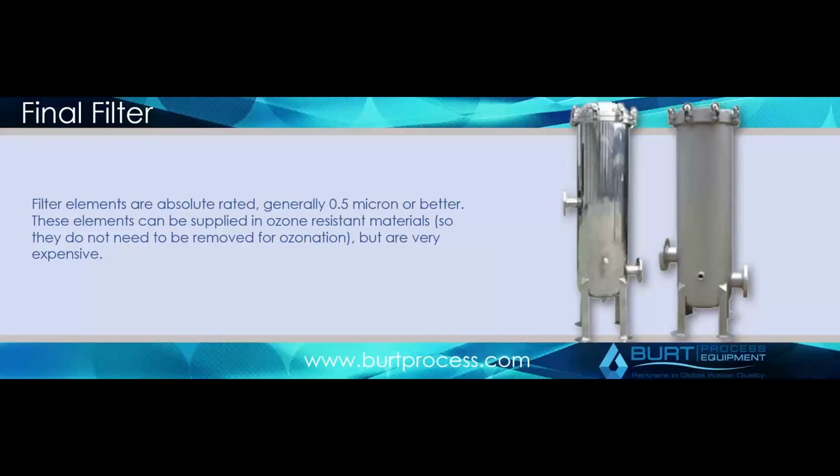And then lastly, one of the more common components in the system is the final filter, generally 0.2 to 0.5 micron or better. And they can go much lower than that, down to 0.03 in those cases. What these are doing is taking out endotoxins, any residual from the UVs or the resin, not the resin catch filters, anything residual in your system. And due to the cleanliness of the water, it's very often that these filters will not be exchanged for almost 6 months to a year in those cases.